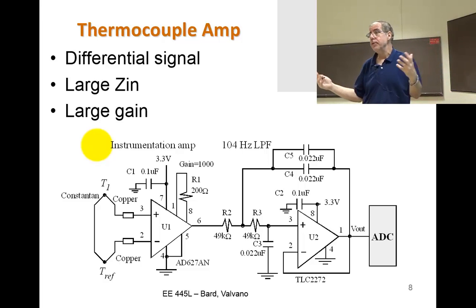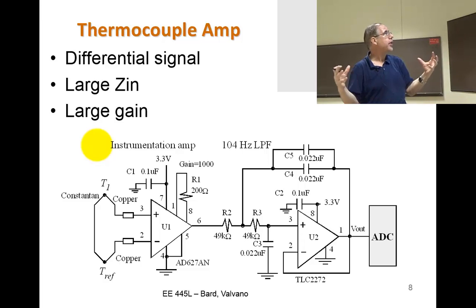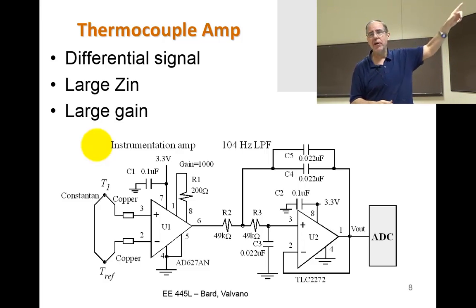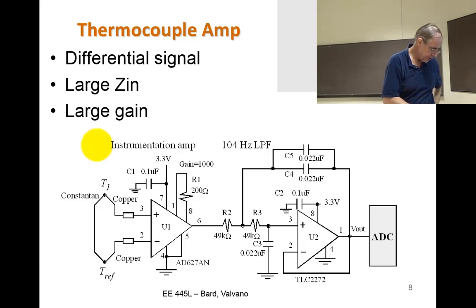We saw thermocouples a couple of lectures ago. We'll use a thermocouple amplifier for 2 reasons. First of all, the necessary condition, it is differential, and the 2 sufficient conditions, we want a large input impedance and a large gain. And we'll talk about the low-pass filter next time.